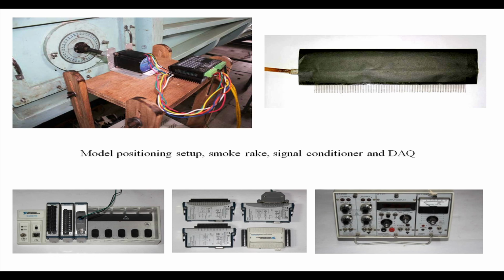So, here we are not going to do any dynamic change, and therefore, the model positioning system, which is basically a stepper motor arrangement which you have over here, would fix the airfoil angle of attack when you are doing the measurements, hold it there, not let it slip, and then once you are done with the data acquisition, again index it further to another angle of attack in steps of say 1 degree or 2 degree, which you have decided earlier. It depends on what kind of resolution you are looking at in terms of the data acquisition.